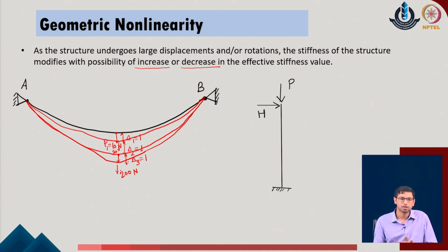Now, one must be very careful while doing this whole experiment, say virtual experiment. We considered that this whole process is carried out with the material being within the linear limit. So, it is not that the material is moving into the non-linearity ranges, and that is where the changes are occurring. The material is very well within the linear elasticity, but what is happening to the system is all due to the large deformations in the given problem.